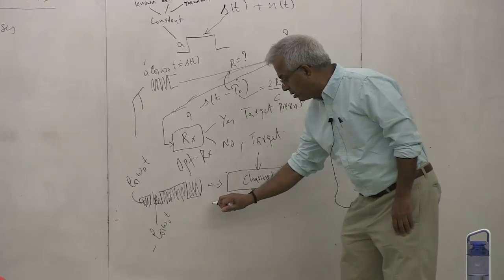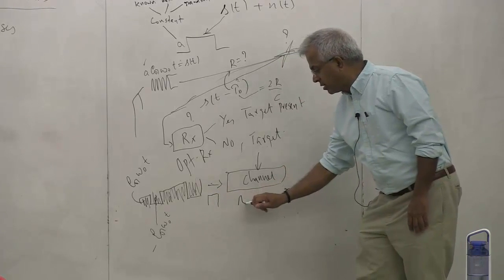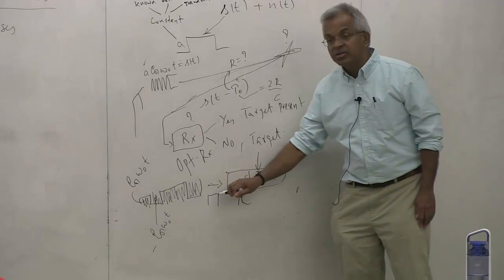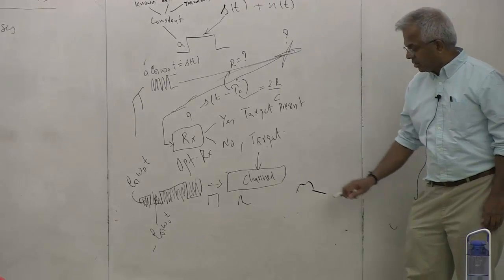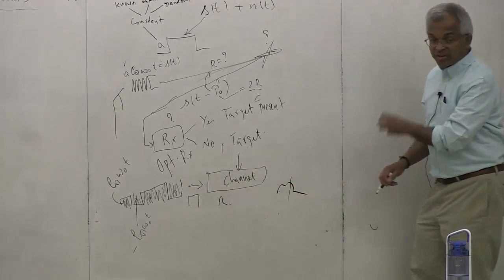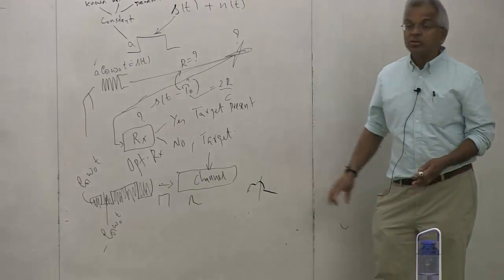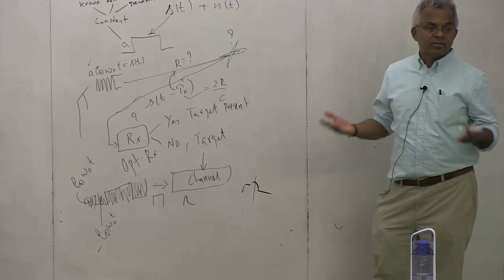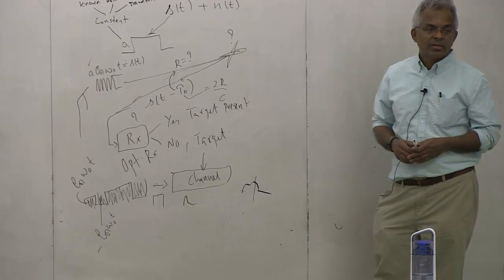So for example, if this is the signal that's coming in and the channel has a small impulse response, the output is this signal convolved with this, so it will be a little distorted. If these pulses are coming one after the other, the first pulse extends into the region of the second pulse, causing inter-symbol interference. So it's one type of interference.